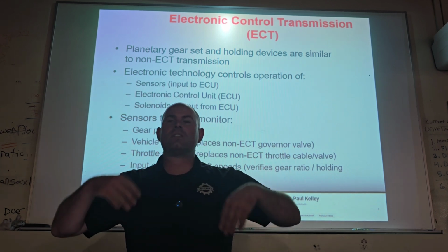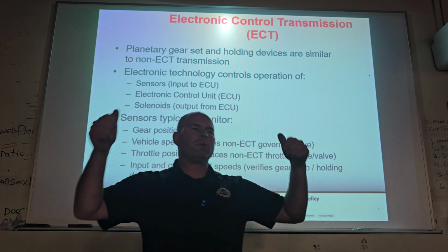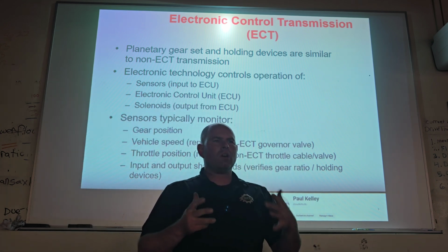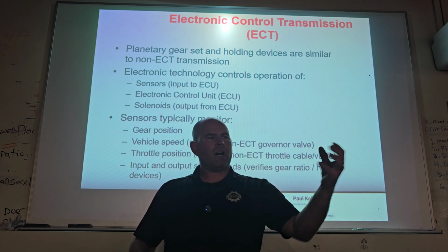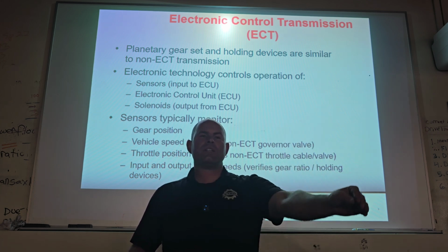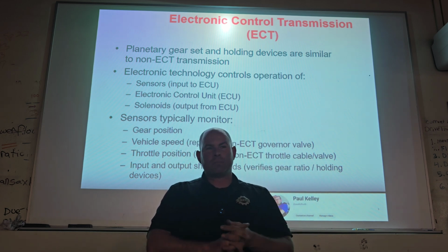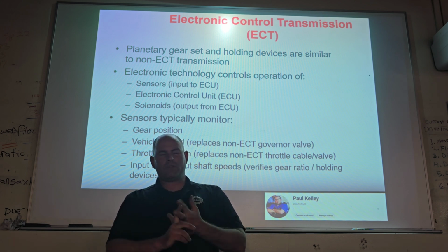The wheel speed sensors monitor the wheel speed. If they see an excessive amount of slip, they report that to the ECU. The ECU interprets it and says, oh, the front left brake is locked up. Let me isolate it. You power up the isolation valve. The isolation valve is moved by a solenoid, right? You learned input, process, output already. You learned it with AC, definitely learned it with brakes.